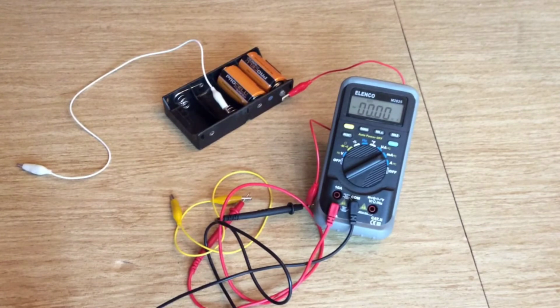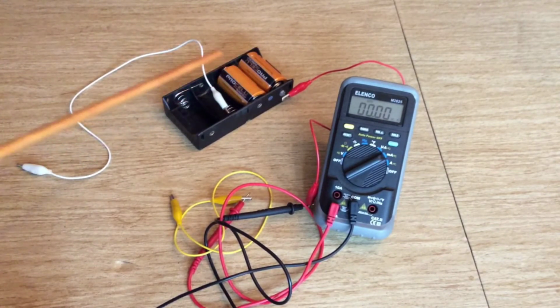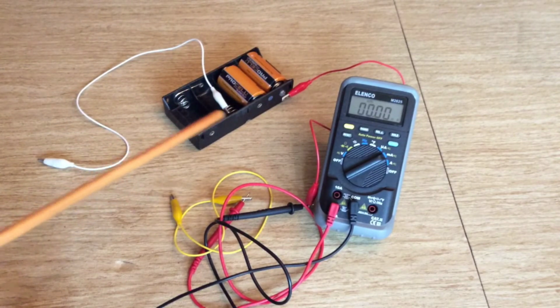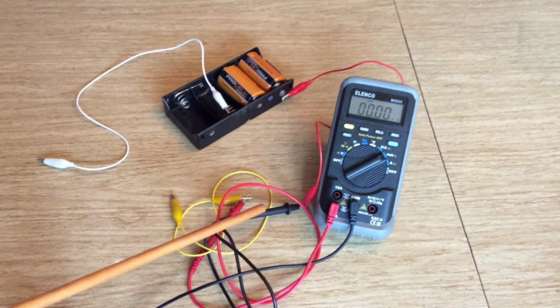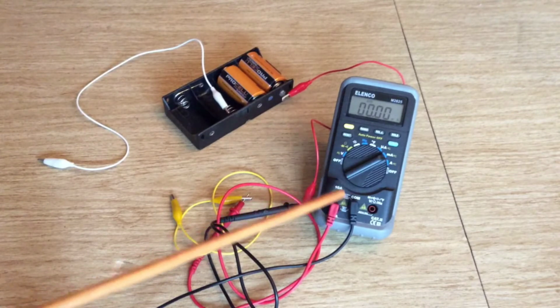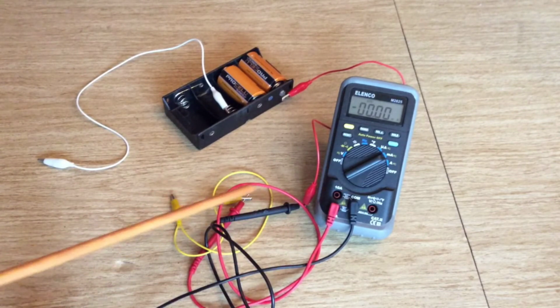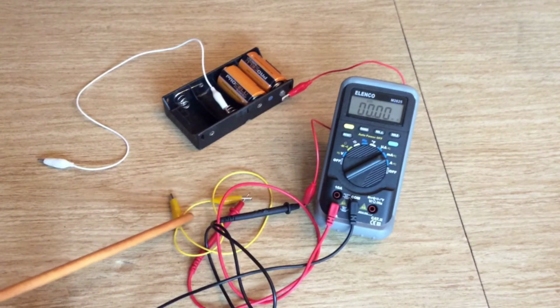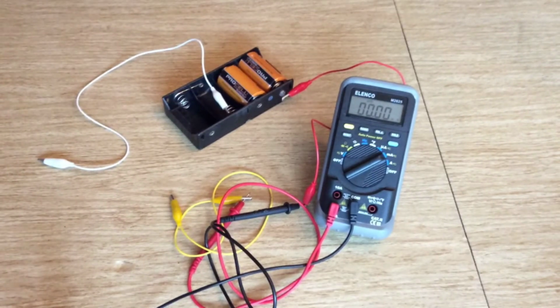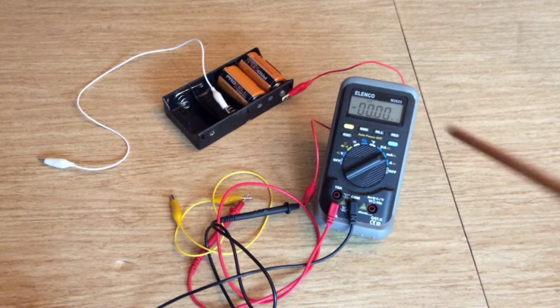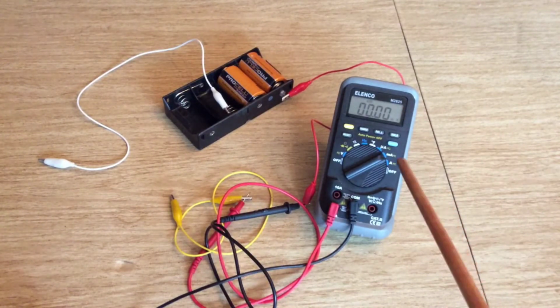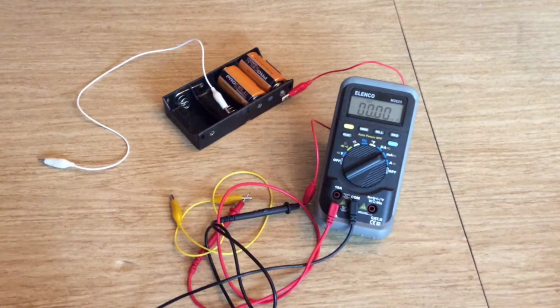Okay guys, it's a little confusing, but let's see if I can walk it through here. I've got 2 batteries here. I've got a white alligator clip that's connected to nothing. I'm going to put a bulb on that one. From the other side, it goes through this red wire to this black wire, which goes into the meter, out the meter's red wire, into this yellow wire, so I can get a clip on there, and that's connected to nothing. And you can see that right now, my meter is reading 0 milliamps. I have it set to the milliamp scale right there.